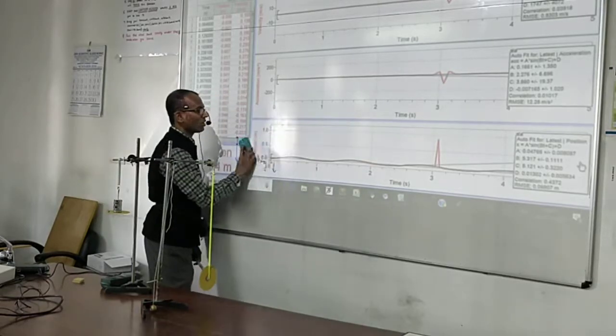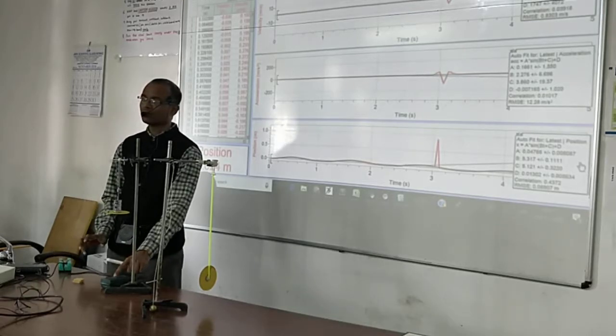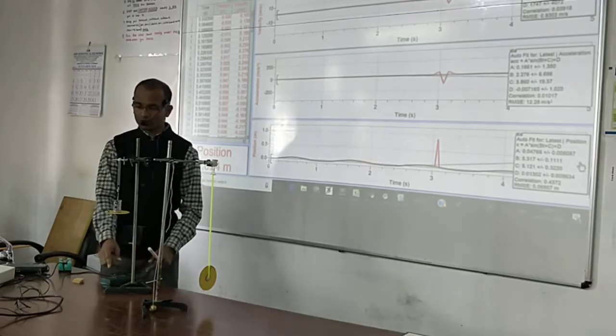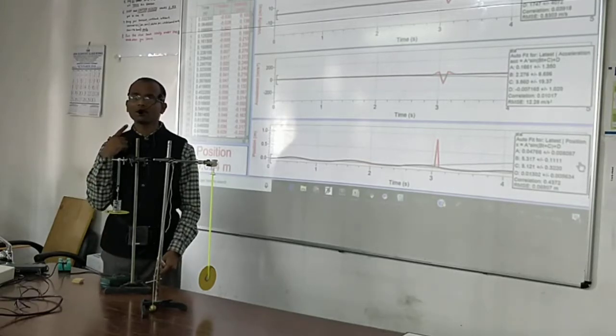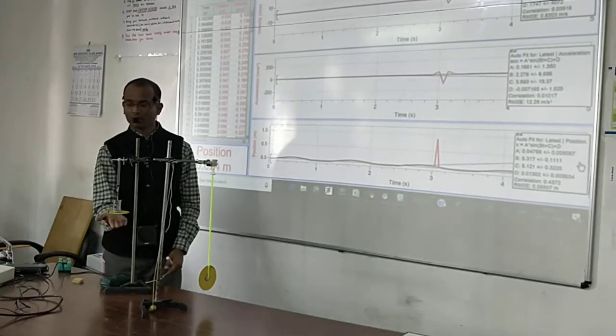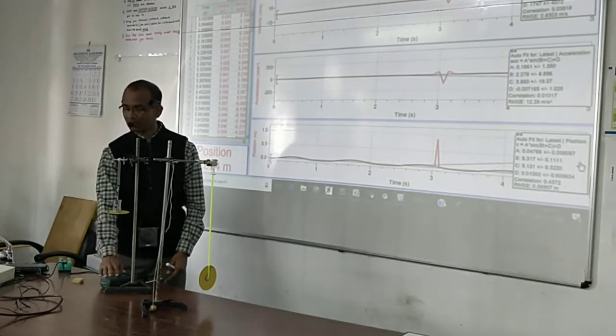So what I have done is I have kept a motion sensor below it. So see how technology is used. This emits ultrasound waves, which we can't hear. The sound waves will hit this card and bounce back. So it takes some time to reach back to this sensor.